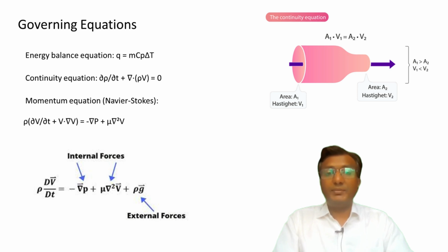The dimensionless numbers are very crucial in analyzing forced convection. As in the previous lecture, we have seen the Nusselt number, which represents the ratio of convective heat transfer to conductive heat transfer, in which h is the convective heat transfer coefficient, L is the characteristic length, and kf is the fluid's thermal conductivity. A higher Nusselt number indicates a stronger convection.